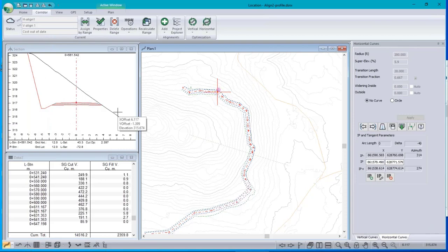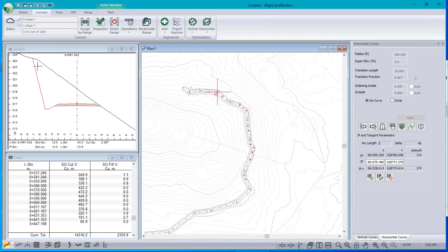Oh, one of the tricks that people often use is they get rid of the ditch. That reduces the volume, and then they slope the road outward so the water drains off. That's good as long as it doesn't snow, because when it's slippery, you slide off the hill, and it's very dangerous. But anyway, there are tricks to reduce the cut volume even further. But given that we must have a ditch, and this is the steepest we can cut the ground, and we must have the road this wide, we have minimized the volume.